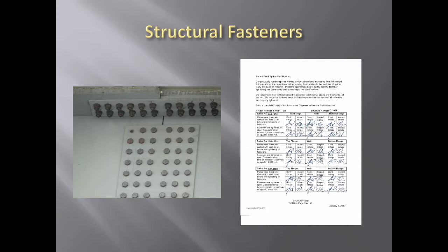As you can see, we've got an issue here. These bolts were installed, but there's one missing. Most bolting experts say that you can't over-tension an A325 bolt. Well, I happen to disagree with that. This structure was actually put in place. Everything looked good. The bolts were all tightened. We go back a few months later and we're missing a bolt. Basically, it was pulled to right at its yield, and then through it deflecting after the deck was put on, it basically broke the bolt and it fell out. So when somebody says you can't over-tension the bolts, that's not true. It can happen, and they won't necessarily break either.